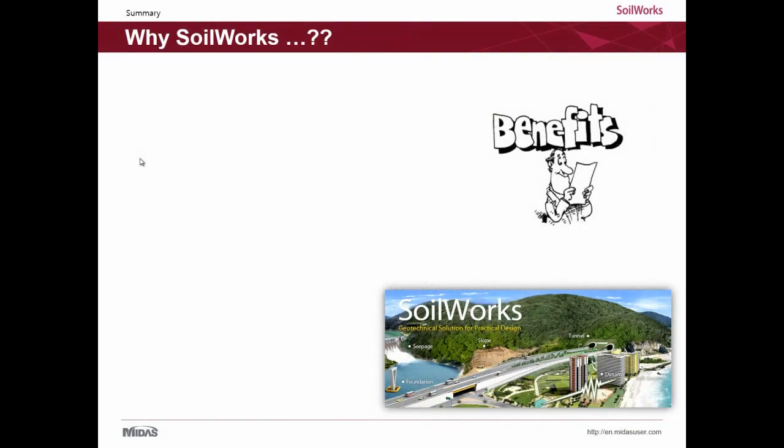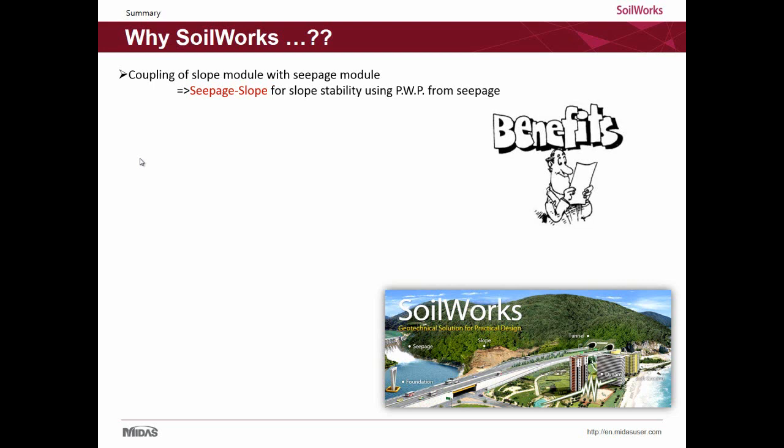Basically, why SoilWorks is beneficial for geotechnical as well as structural engineers. Well, coupling of the slope module with the seepage module is possible in SoilWorks. That is because the seepage slope stability analysis can be done by taking the pore water pressure from the seepage module.